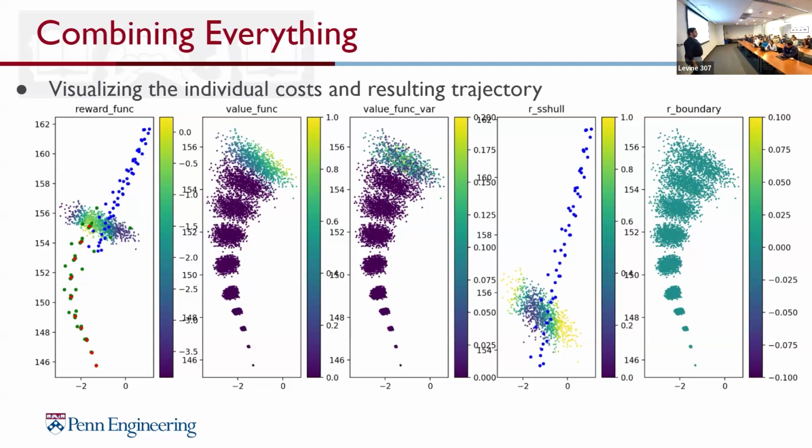I saw that you filter out unsafe trajectories, but how do you actually figure that out? Right. Because we have a distance measure on violation to each of the sets that we want to stay in, we have an easy way of checking whether or not a state is safe. Once we've sampled the trajectory, like in this case, we can see if the trajectory goes out of bounds, and we can just check that because we know the states after we've sampled. You can be more robust in your filtering if you have some uncertainty in your model and be more strict in the filtering that you do. But that's just a trade-off.